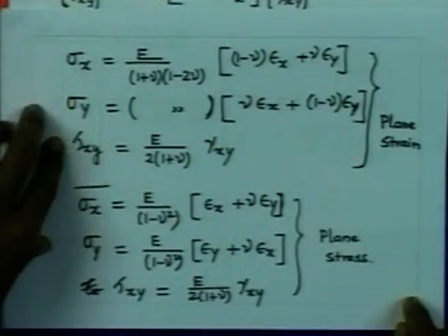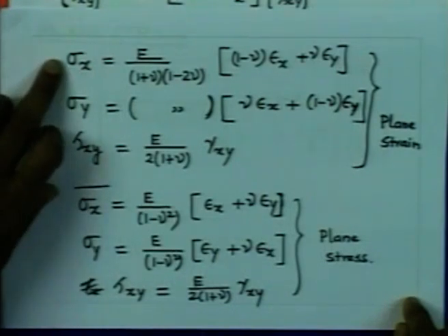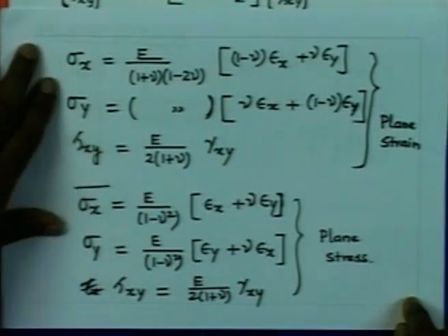Plane stress is going to be seen in situations where we have thin plate like objects loaded in its own plane, and plane strain condition is going to be seen in situations where the object is very long and the loading is having some continuity and symmetry in the axial direction. Then in that case, in each plane there will be plane strain movement only, all the points are going to move in the same plane, and therefore, the situation is again characterized by the 3 stresses.